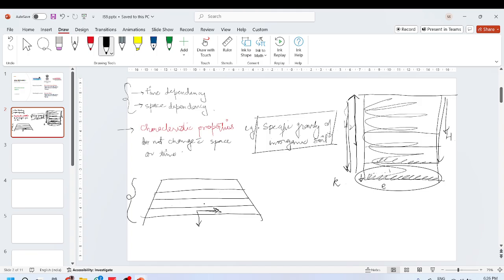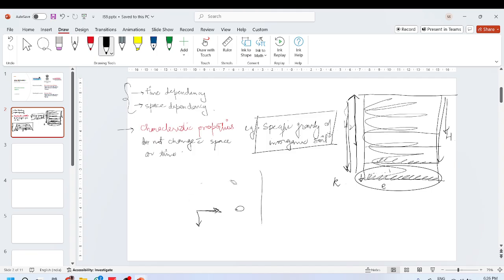It does not have the same properties. So as you see, based on the position, the property is changing, isn't it? So in a field, if you want to model this, if you want to understand what will be the permeability here, you have to take into account the location or the position of this property, which is why we develop these seepage nets, we develop these flow nets.